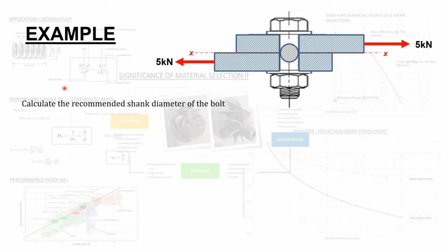To calculate the shear stress yield limit, that is approximately 58% of the yield stress. So 58% of that would give us some idea of what the yield limit would be in terms of the allowable shear. So let's proceed to work along this problem together.